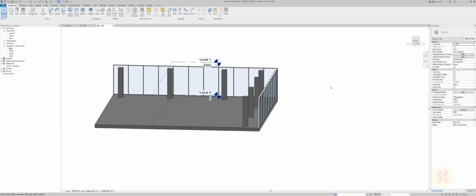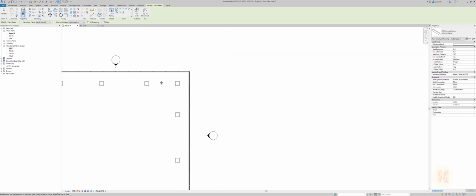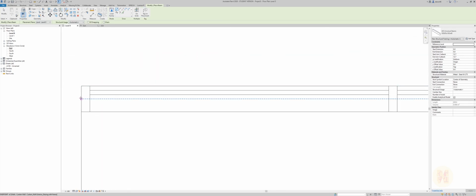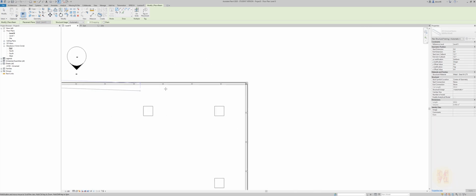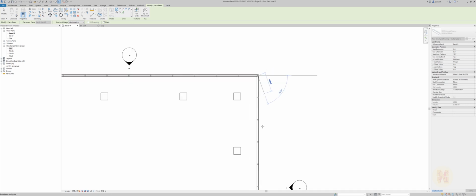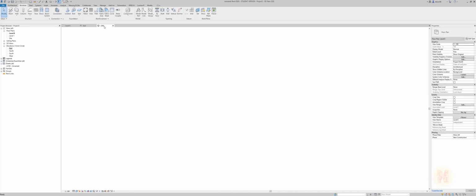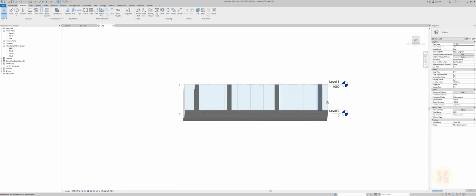Now we need some system, we should create the beams. Let's go to the structure. Here we will find the beams, and here we have only one type of the beam. But we now will use this type of the beam. I will go back to the level 1, level 0, and I will draw my beam here. Let's draw one beam to that side, and let's draw the second beam to that side. Okay, done.